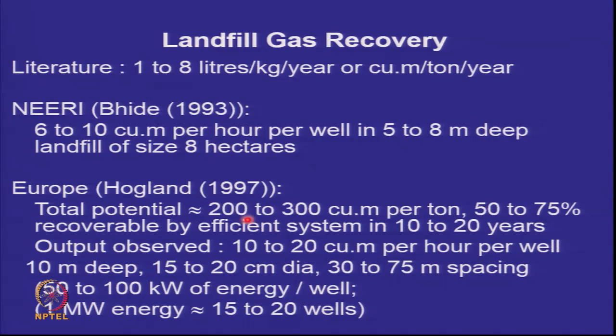Also look at the depth. Here they were talking of 5 to 8 meter deep landfill, and here they are talking of 10 meter deep landfill. And they typically have gas wells at a spacing of 30 to 75 meters. So if you have 15 to 20 wells of this kind, you can generate 1 megawatt of energy for 20-25 years. That's the European experience.